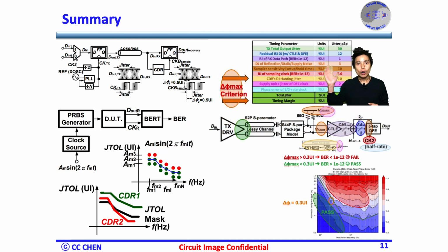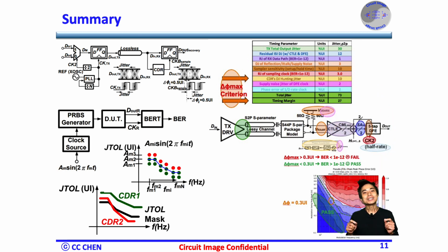Hopefully, we already have the link budget knowledge of the eye width and know we could translate the target bit error rate to the final eye width margin or the input jitter tolerance. So we could even plot a phase error based jitter tolerance, which we call a pseudo jitter tolerance here.